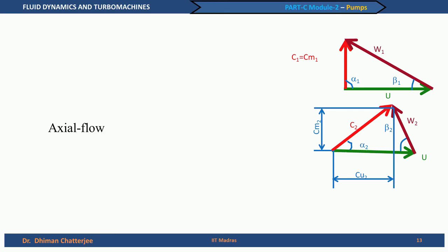For an axial flow machine, please note that the derivation that I am trying to show you to bring out the effect of the blade angle need not be restricted to axial flow. You can do the same derivation for radial flow pump as well, but the calculations will be more cumbersome. To bring out the physics, the significance of the blade curvature, it suffices to take the axial flow pump and the assumption of C1u equal to 0. So, u2 equal to u1, and hence W_BL infinity is u times C2u, which we have already done.